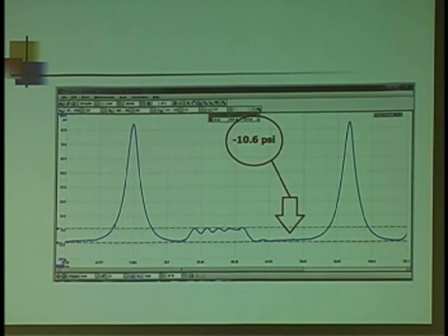This will let me see both cams for that cylinder. What about here where I'm measuring now with the intake? Got a minus 10.6 psi measured. What am I measuring? Manifold vacuum, right? If I had a MAP sensor on this engine, wouldn't that be what it'd be reading? Isn't that the absolute pressure?